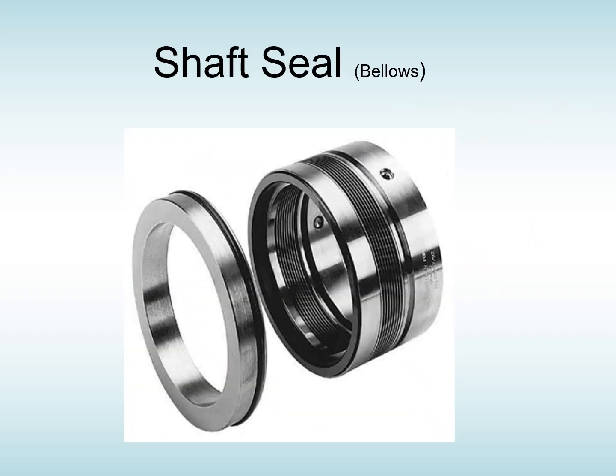Quick look at a shaft seal. This is a bellows type shaft seal. There are many different types. Here we have O-rings, one internal, one external. We have a carbon face, which is on the rotating part of the shaft seal. And we have the locking screws, which lock the rotating part onto the shaft. And the other part here is the stationary steel.